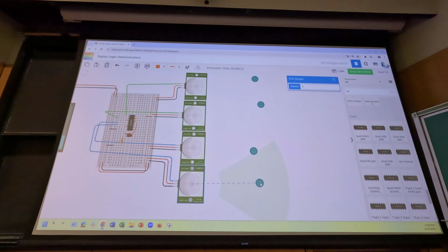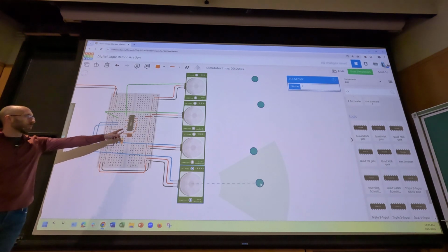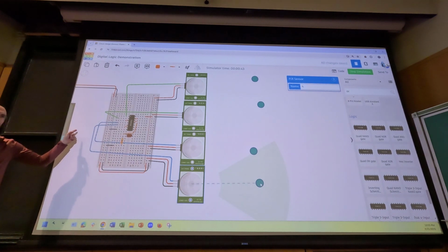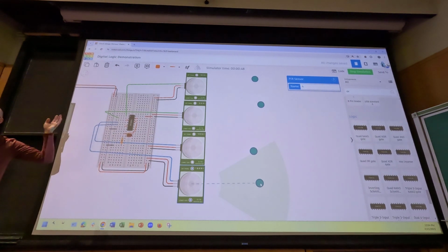Again, we use the OR gate as an example here, but there's a whole list of these. I will add more to the written notes. There are about 4 more that are going to be in that big table that I didn't want to spend lecture time copying down today. And the motivation here: we are using this to turn on an LED, but if you wanted to combine all of these 4 sensors and feed it to a single Arduino pin, you could do that as well. This orange wire would just go over to your Arduino, and then you only need 1 pin change interrupt instead of 4 to detect if any of the sensors went high.